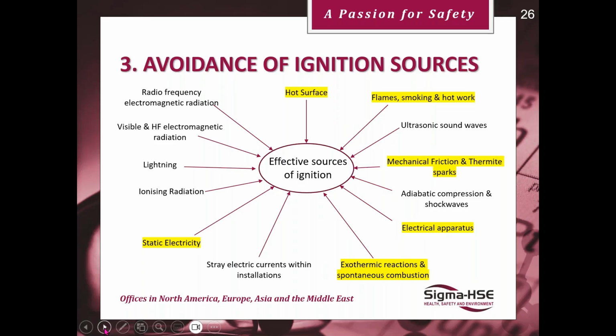For your information, thermite sparks occur when aluminium is in contact with a surface like rust. In other words, if you have an aluminium ladder, and it strikes against a rusty beam, a thermite spark can occur. And these are above a joule in energy, so they're extremely incendiary.